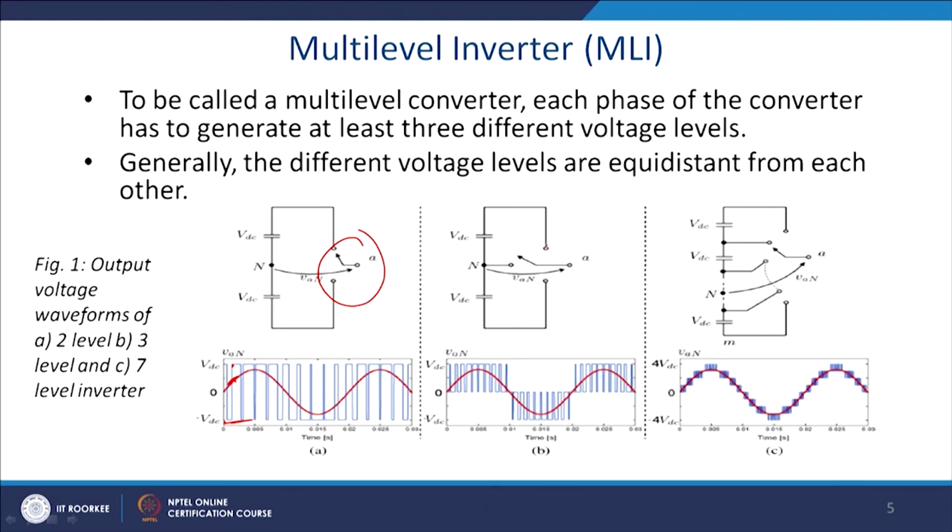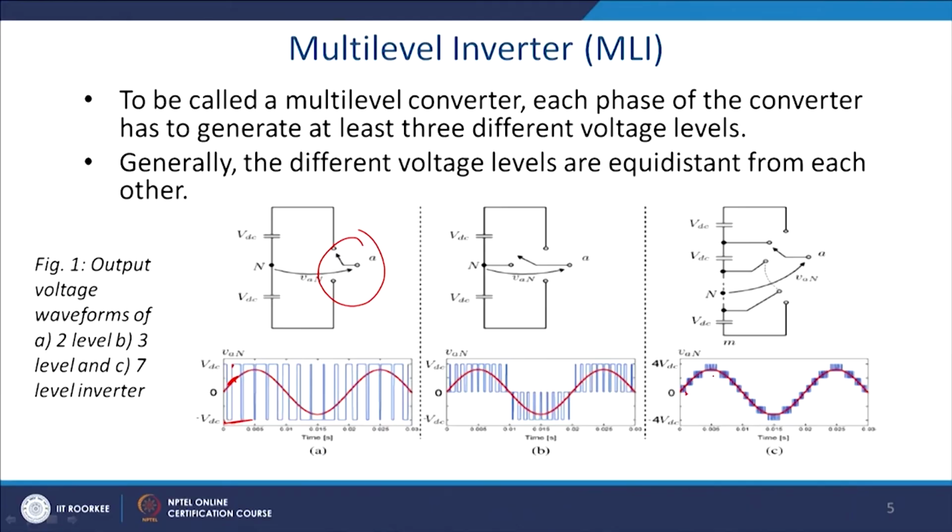It can be connected to VDC, or it can be connected to 0, that is the midpoint of the DC link capacitor voltage, compared to the lower end of the switches. Thus, you can directly see that the stress here is halved, and the instantaneous voltage error has also been halved. With the multi level inverter, you can see that this error is minimized greatly.